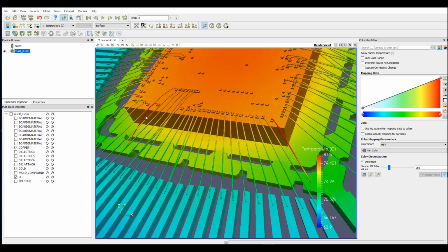So the user can determine if those wires can sustain a certain temperature, or will break, or, together with the power inside the silicon chips, assess the overall thermal response or thermal profile of this package if they put this package on the JEDEC extender board for thermal characterization.